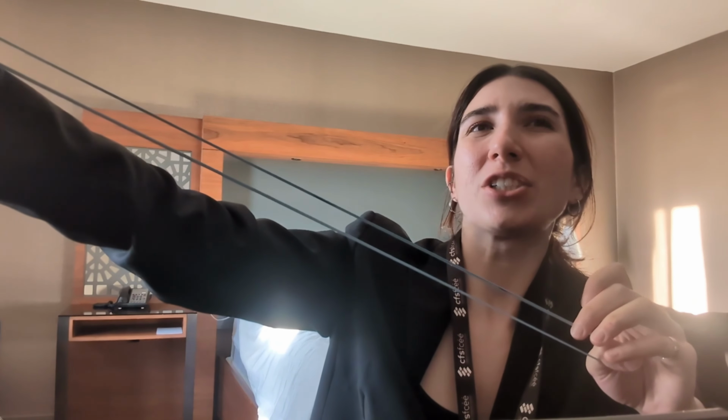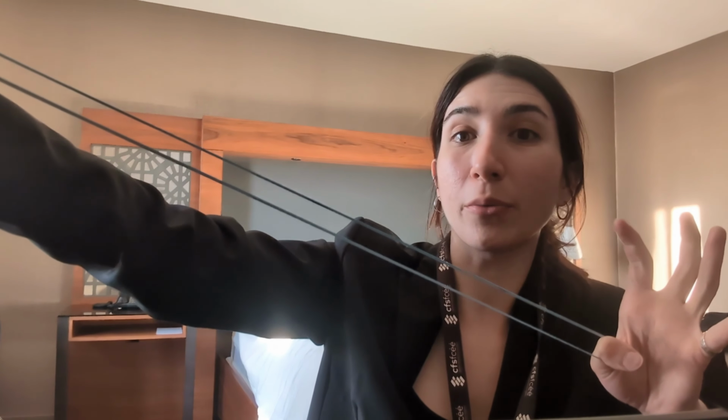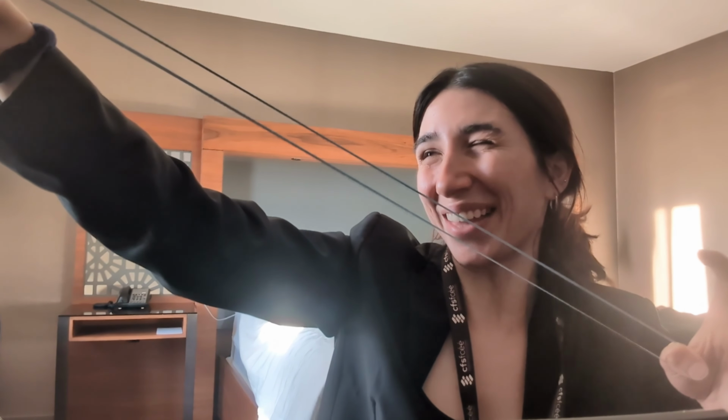This strain measurement tells us if a material will stay in its elastic deformation, so when I stretch and let go, it'll bounce back to its original shape, or if I stretch that material so much that I'm now in the plastic region, where it either deforms the original shape, or fails and rips, which I'm kind of scared to do right now.